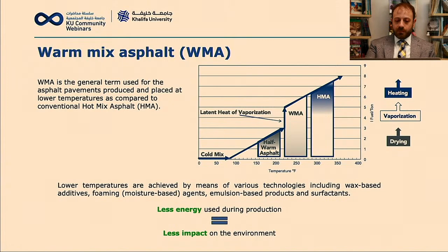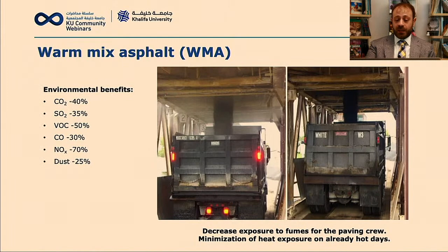But this is not the only benefit that we can take from the use of warm mix asphalt. There are other benefits. Here in this slide, in this picture in particular, you see on the left side a truck that is being loaded by hot mix asphalt, so produced at very high temperature. And on the right side, there is a warm mix asphalt. You can see by yourself that by using warm mix additives, we are also able to decrease the exposure to fumes of the paving crews and also minimize the heat exposure on already hot and warm days.